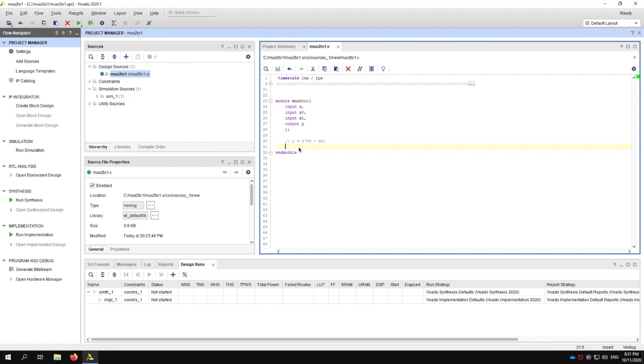The way I do that is with the wire keyword, and I'm going to define a comma separated list of signals. I'm just going to give them human readable names, but I, as the designer, define the names of these signals. They're comma separated, and I terminate the statement, as always, with a semicolon.